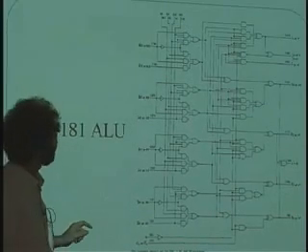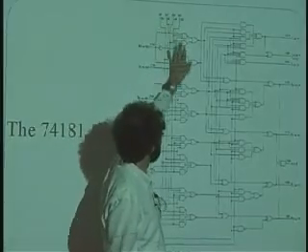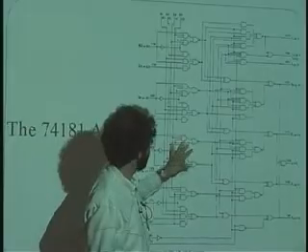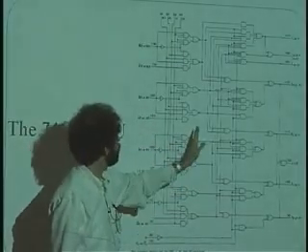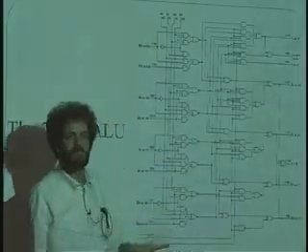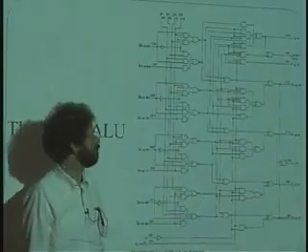And it turns out that if I just fix this code with the code for add, what you would find is that the G and the P that gets generated by the logic function right here, and notice this is a sum of products form, here's the OR gates, here's the AND gates, here's the NOT, right? Okay. Each of these things will in fact be the generator for doing G and P.